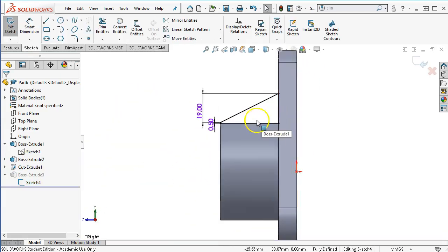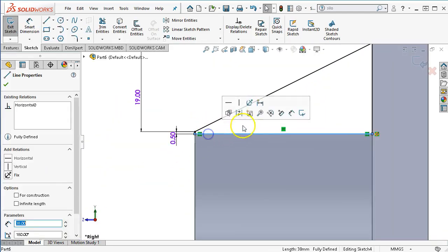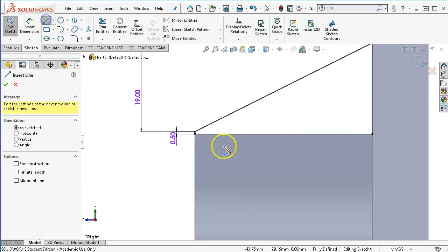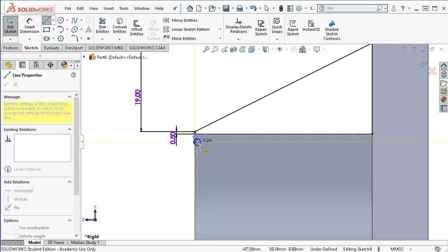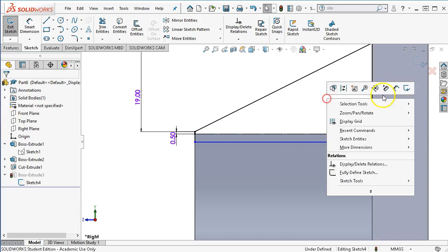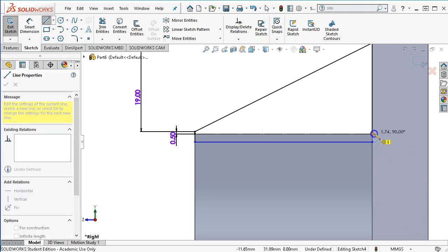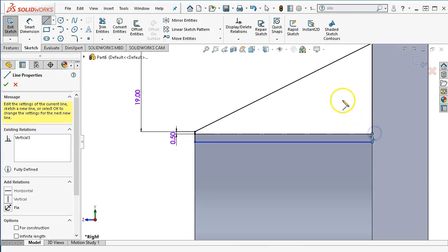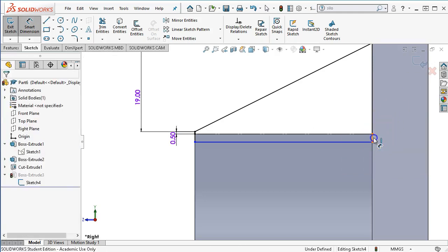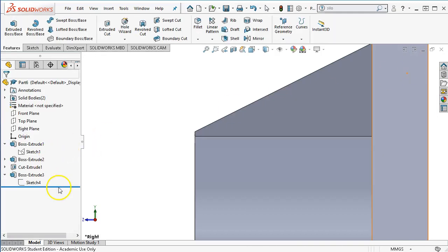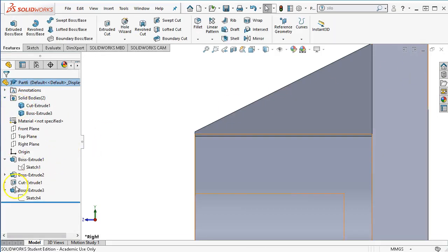So let's edit the sketch. And even though I built that one out that time, we really need to have an intersection into the part to make sure that it has that overlap. Oh, it didn't finish. Okay, there we go. And we'll put another 0.5 millimeter on it. Go ahead and accept it. And it will still be two solid bodies because I unchecked the merge result.